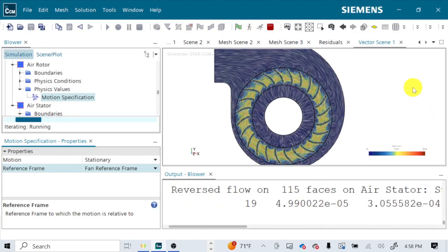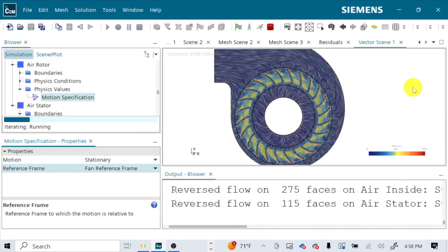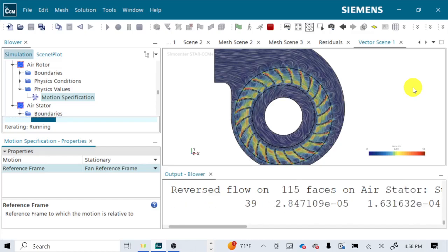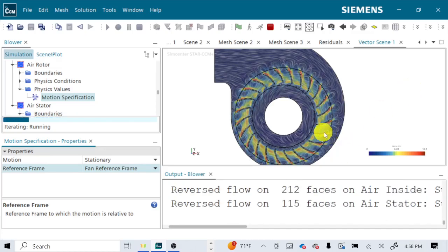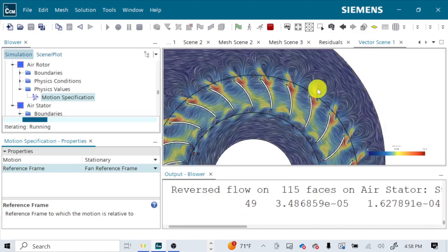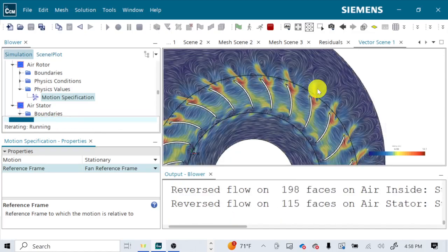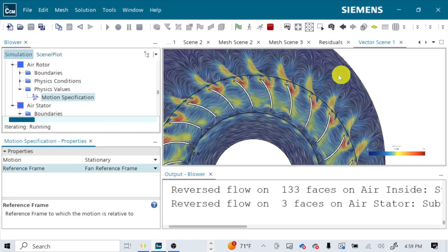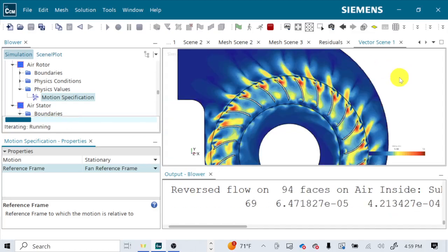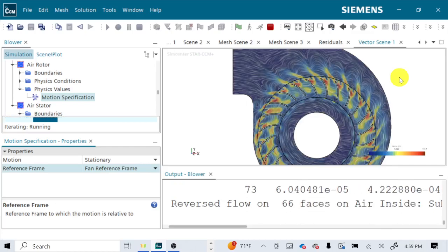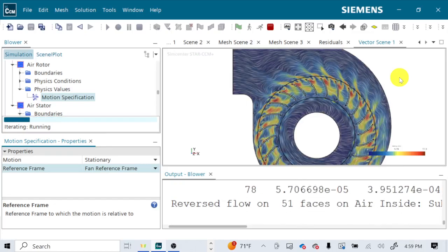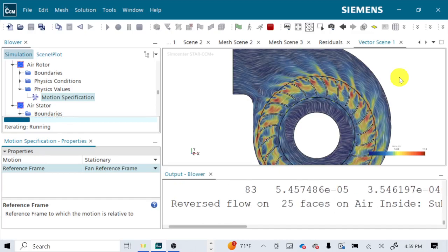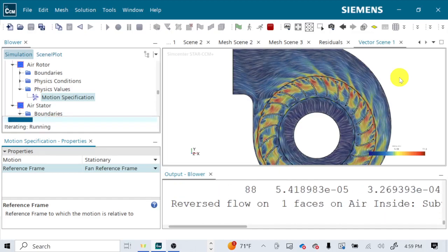And oh, hey, look at that. If we tell the simulation to run, it's figuring out that, yeah, flow is coming in and flow is being shoved out through the outlet here. And it looks kind of weird, honestly, because it's figuring out how these reference frames are interacting. But literally all we've done to force any of this flow is just tell it that that inner region is rotating. And it's doing everything else based on that.